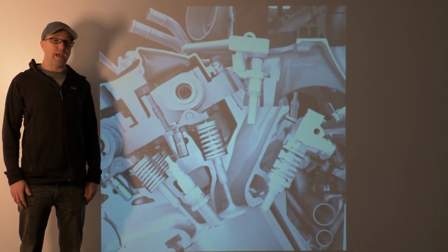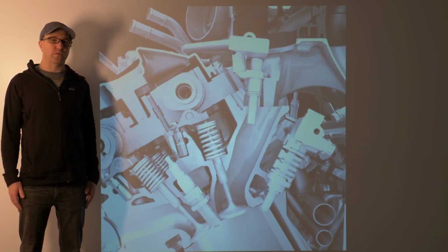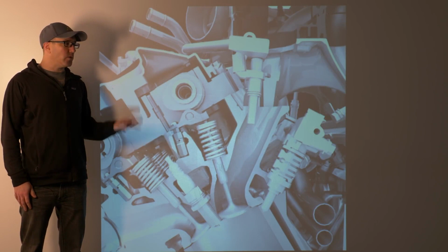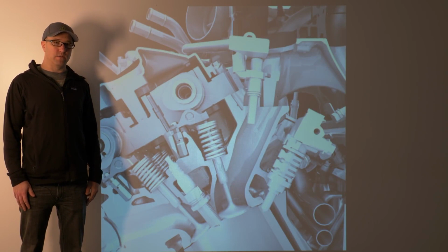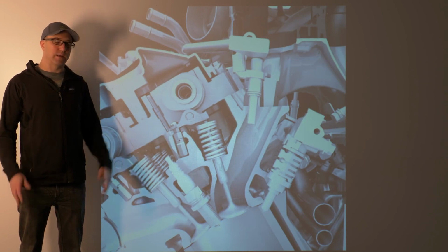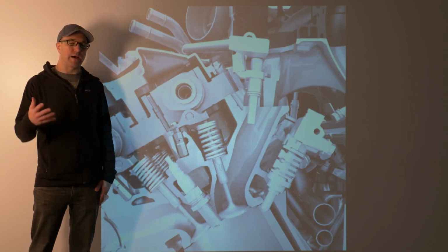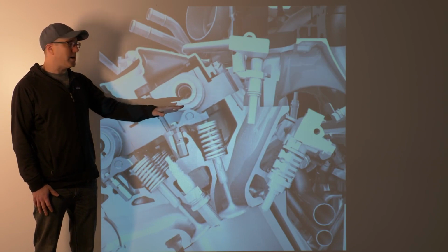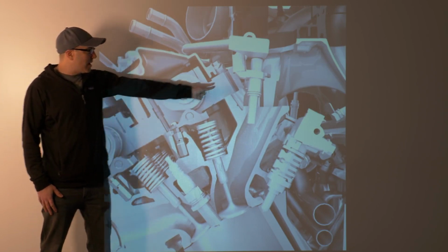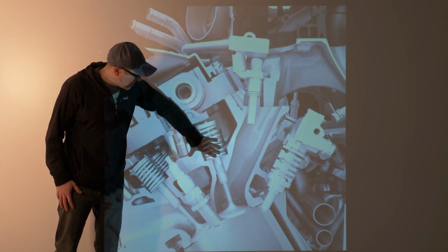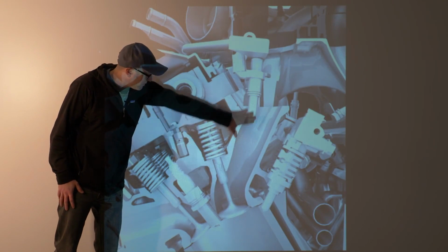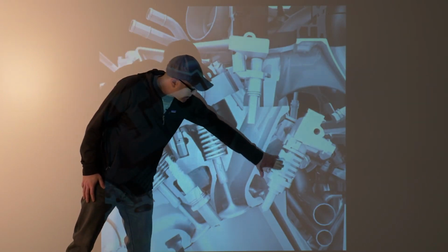Now you know what port and direct injection looks like and how it works. There's a third iteration. Toyota has kind of mainstreamed this on their cars, and more vehicles that they have are starting to do this. Ford is also starting to mainstream this on their cars and moving away from direct injection only. Of course, it's not going to be on every motor because there's a lot of cost associated with it, but this is when you combine port and direct injection. You have a port injector here that sprays into the cylinder head, and you can see that it sprays onto the back side of the valves. This is where the fuel is going. And then you also have direct injection here, which sprays into the cylinder directly.